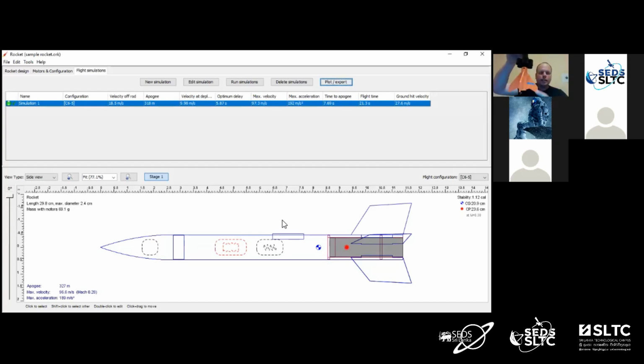So we would ignite that booster motor. These little black powder motors are in what's called an end burner configuration, so the propellant burns from bottom to top, or back to front, however you want to look at it. When the propellant burns up to the top in the booster stage, that will ignite the sustainer, or the upper stage. That pressure will knock the bottom off, and then the sustainer happily goes up on its merry way.